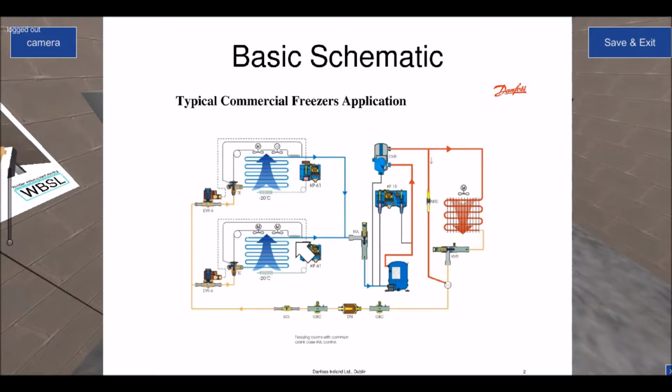and you will find that your superheat constantly moves between that parameter. And what actually happens is that if you can keep the doors closed and you have everything down in temperature, this valve is designed to sit at 6, to give you a constant superheat of 6 degrees. So it tries to sit in equilibrium. It tries to sit in the middle at all times. It doesn't want to be fully open. It doesn't want to be fully closed. It wants to be at equilibrium. It wants to be in the middle.